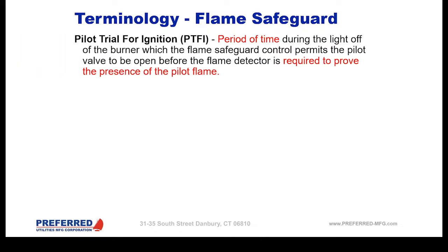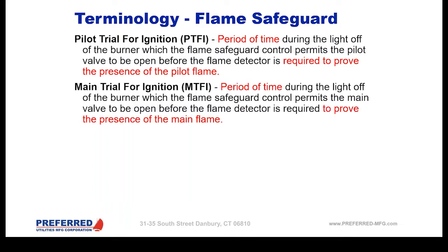Pilot trial for ignition. PTFI is what you're going to hear as the terminology there. That's the period of time during the light off of the burner, which the flame safeguard control permits the pilot valve to be open before the flame detector is required to prove the presence of the pilot flame. Main trial for ignition. This occurs after PTFI, so after the period of time during the light off of the burner when the flame safeguard control permits the main fuel valve to be open before the flame detector is required to prove the presence of the main flame.